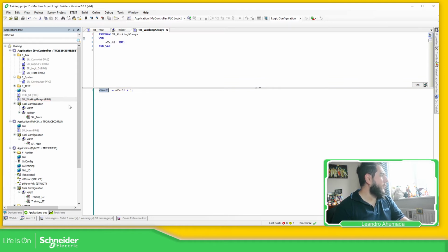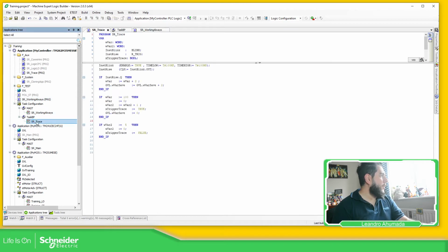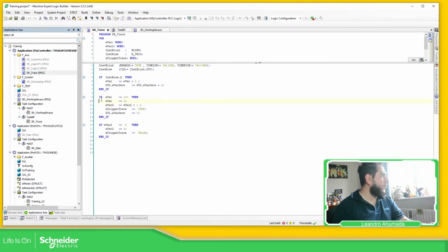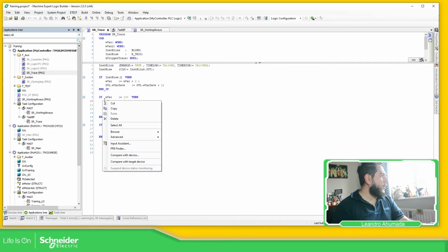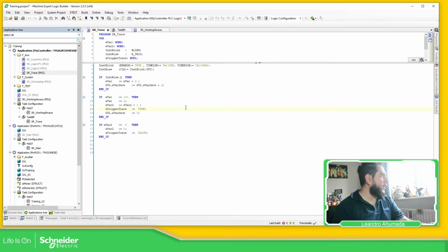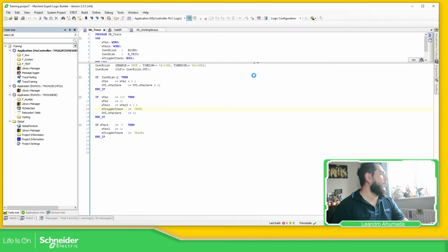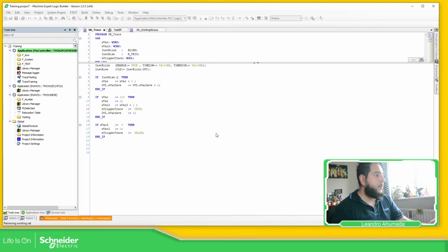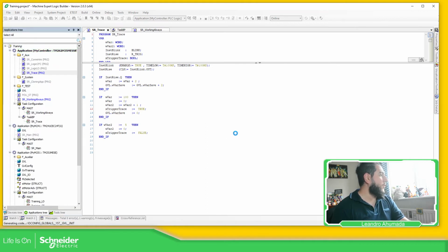So what I'm going to do is call this POU in a different task, in the principal task that I have. And here in the trace, I'm going to create a breakpoint over here. Let's create a breakpoint. Cannot use it. Let's log into the controller. This one is the real controller, it's not a simulation.